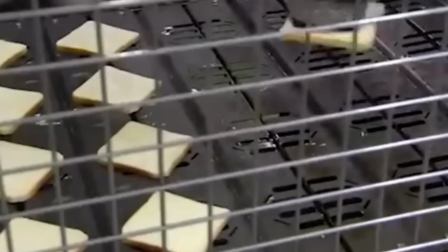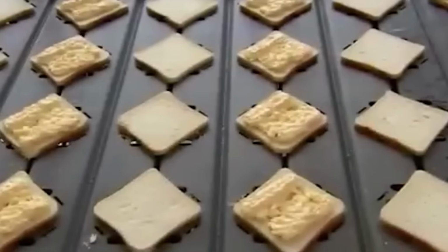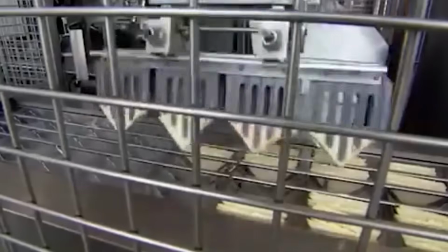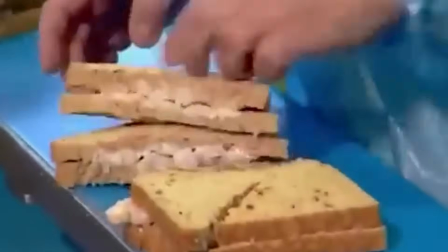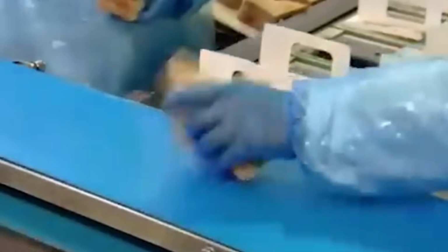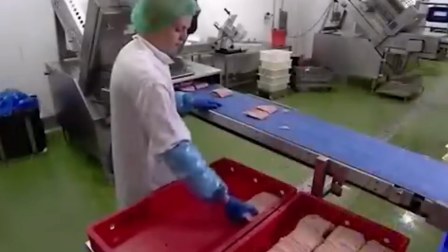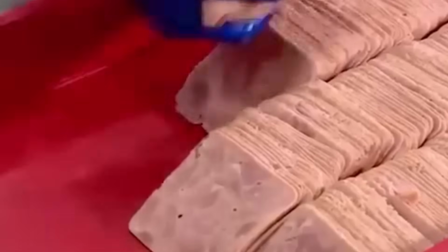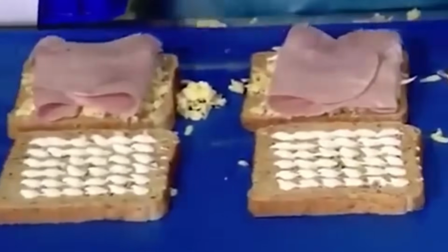Now fully assembled, the sandwich proceeds to the slicing station, where high-speed rotary or ultrasonic blades divide the product into the desired shape, typically halves or triangles. The slicing system is mounted on actuators that follow the motion of the sandwich as it moves along the belt, ensuring the blade enters and exits the loaf cleanly without tearing or pulling. Blade tension, sharpness, and angle are maintained through automated diagnostics, and the entire slicing module is flushed and sanitized between